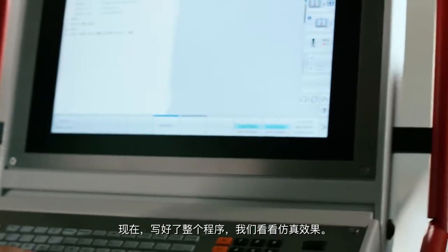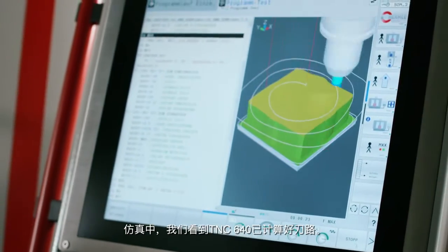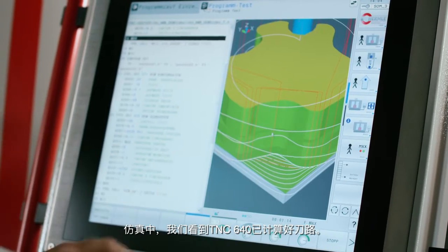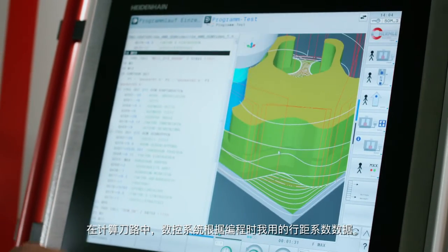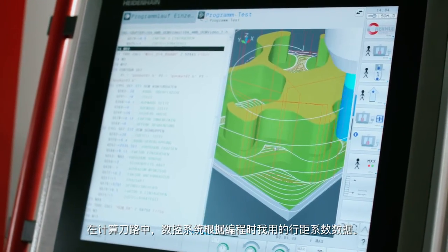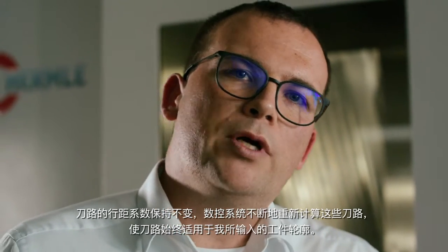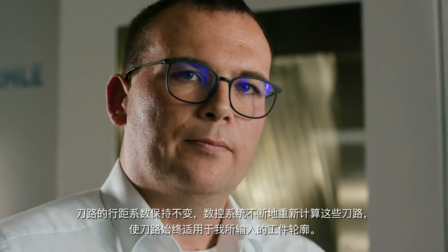Now that the entire program has been written, we can look at the simulation. In the simulation, we can already see the tool paths calculated by the TNC 640. These paths are calculated based on the path overlap values that I prescribed while writing the program. This path overlap is maintained constantly, and the control continuously recalculates these paths so that they are always appropriate for the workpiece contour that I entered.